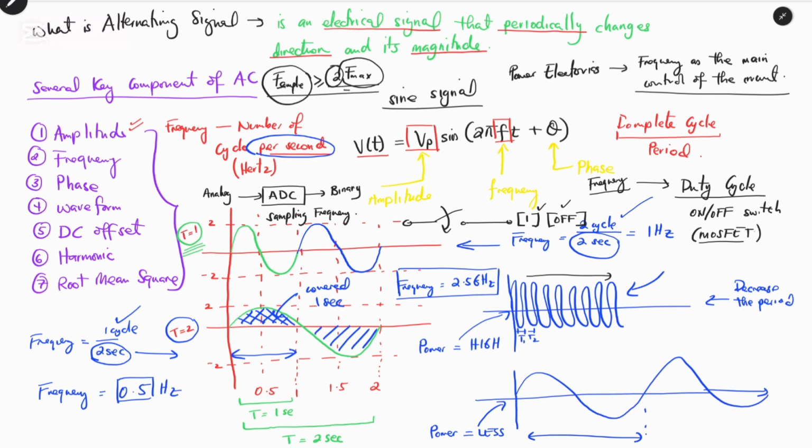For example, if the maximum frequency is 60 Hz, that means the switching for the sampling must be 120 Hz. So the acceptable sampling frequency must be greater than or equal to 120; 140, 1000, 10,000 and above is acceptable. But 110 Hz, 70 Hz, all of these are not acceptable. So we find that understanding what a frequency is can be applicable in many areas in electrical engineering.